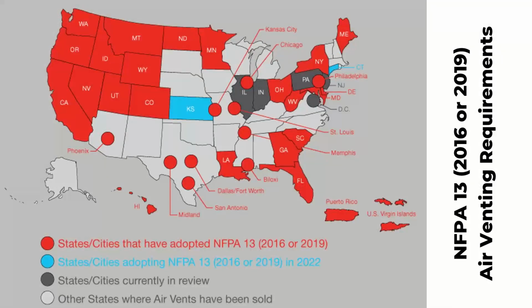Now, most major jurisdictions, when we produce these maps, the minute we make them, they're almost dated. Most major populous jurisdictions around the country now require air vents on all wet installations, in addition to what is shown on this map. Besides state mandated installation requirements, most major markets, even if your state level does not require it, and establishments such as the retail trade and the wholesale and distribution industry, have mandated it regardless of state code, because they know that by cutting down on corrosion they're going to get greater longevity in their sprinkler system.